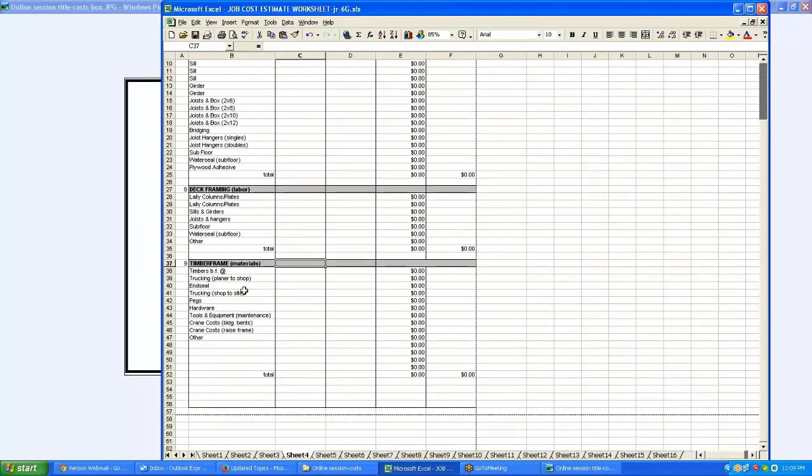We have materials. With deck framing, he usually built a conventional 2x deck. He'd buy lally columns and steel plates, and then he'd put up sills and beams to hold them up, joists and hangers and subfloor, and then he'd stand his timber frame up on that with a pocket in the corner for the post to go down and sit on blocking.